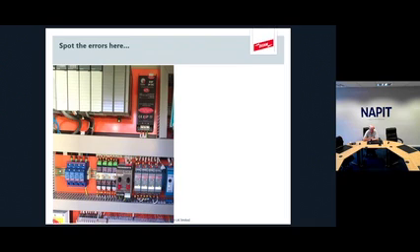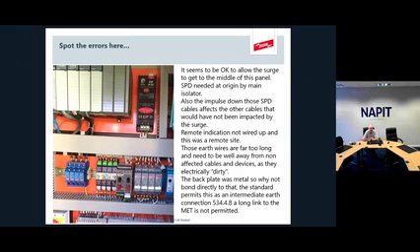So be very mindful about where you're locating them. And that was everything that I was talking about there. You've got to make sure that your output and input cables don't overlap. And just the final thing is that when you do have cables coming into an SPD, and then you've got dirty or drain cables or earth cables going away from the SPD, don't mix them up. Otherwise, you're going to have a whole lot of problems. You're going to need more SPDs than you would think about.